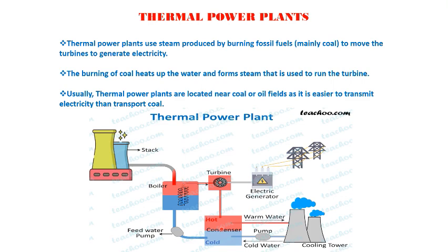And this warm water is also transported to this cooling tower, and this cooling tower converts this steam to normal water, meaning the temperature is reduced. This water is also transported through this pump and proceeds here, and this cold water is also transported along this to this main boiler.